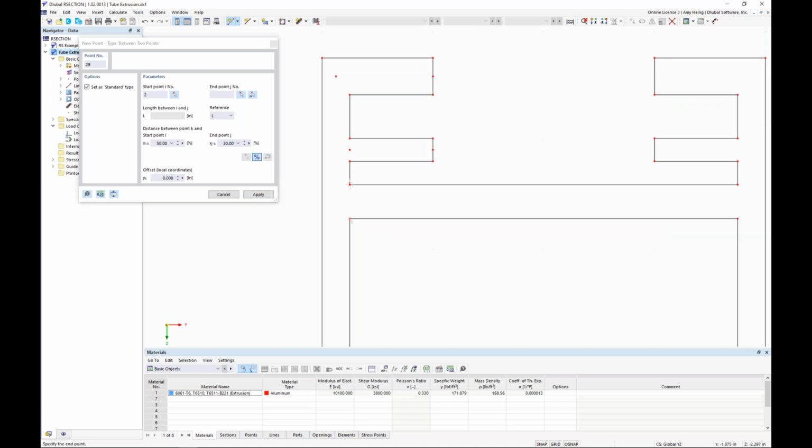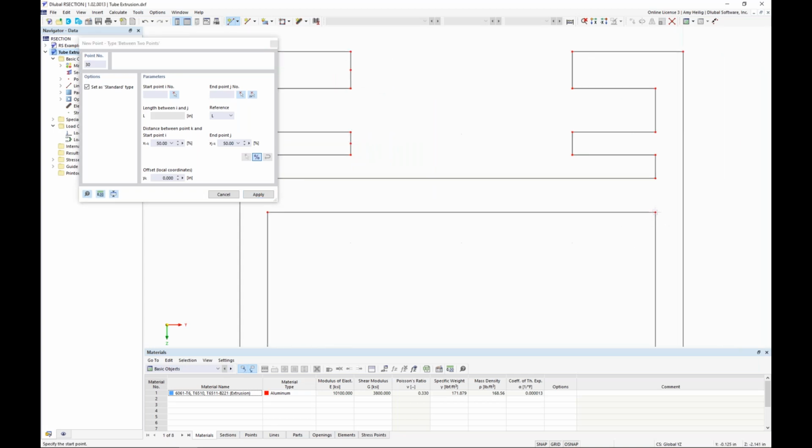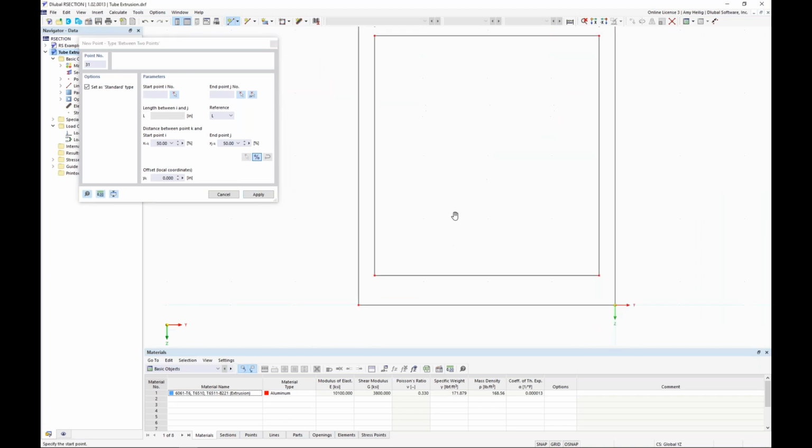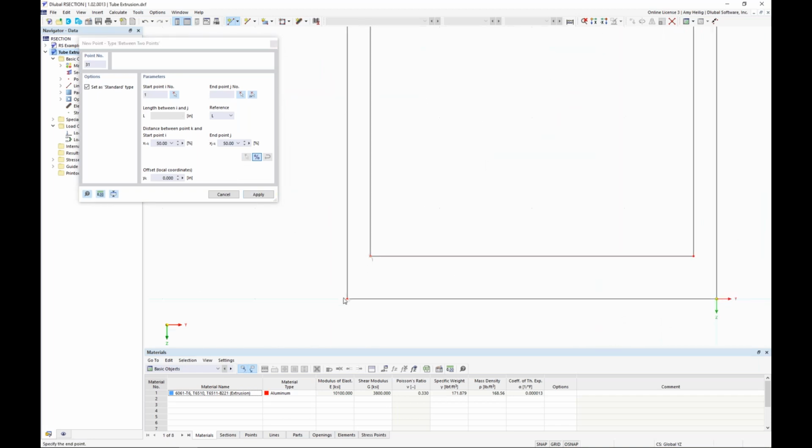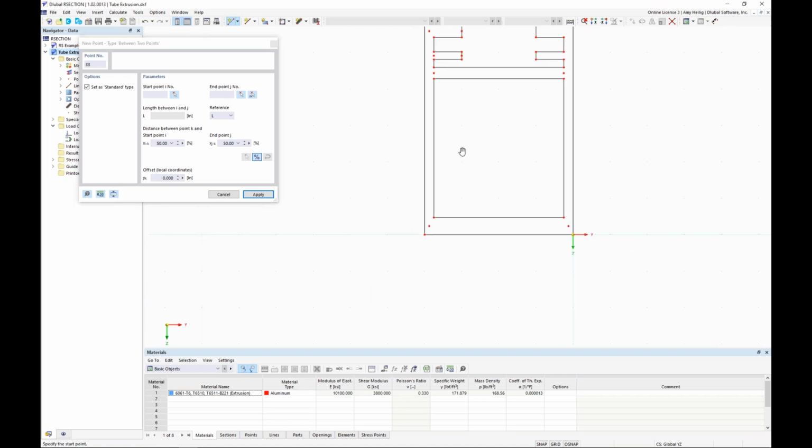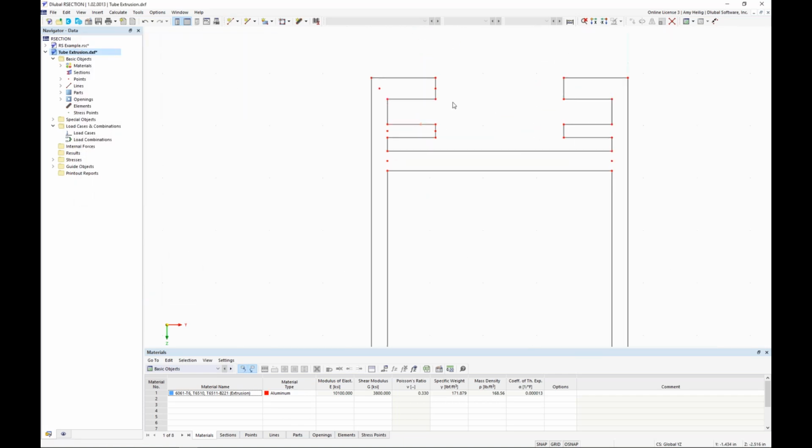We'll do so at this 3rd horizontal location as well as on the right side here. So clicking my first point, my second point, and finally we have a couple points down here at the lower left that we would also like to generate. So once we have completed the generation of the nodes, now notice I'm not creating these same nodes on the right-hand side. We'll be able to mirror our elements from the left to the right-hand side to save us a